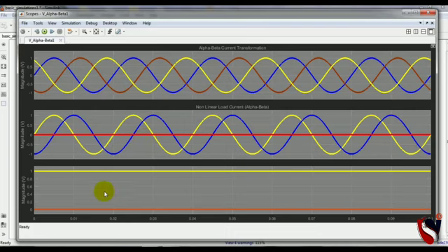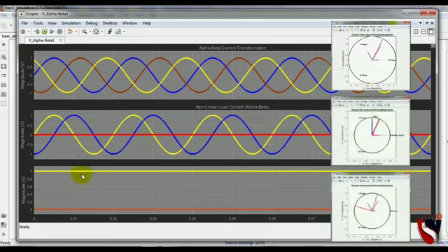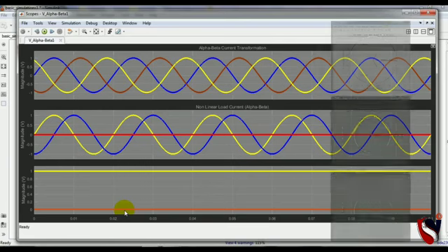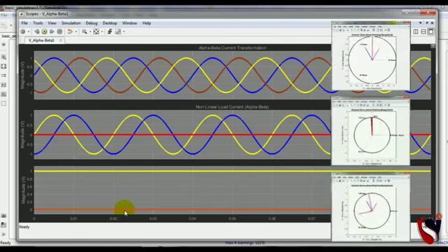You can see this is the DC quantity again, and I am going to show you the graphical representation here. You can see in a window how the 3-phase vector, which I just showed in the program, works on this principle: how the 3-phase system is converted into the 2-phase and DC values. I told you the advantages: first, alpha beta has the advantage that you can control only the 2 phases, and the measurement instruments are reduced, and the wiring is also reduced, because ultimately you are controlling the 2 phases, and the 3rd phase is indirectly controlled by alpha beta.